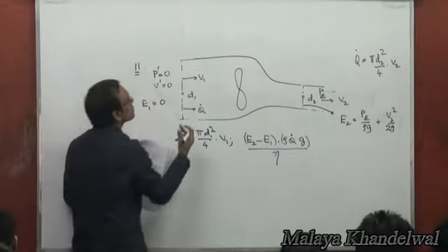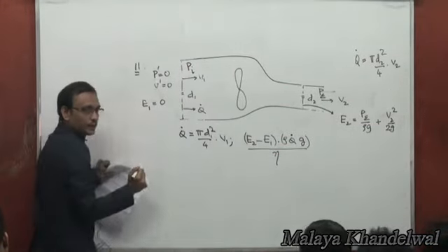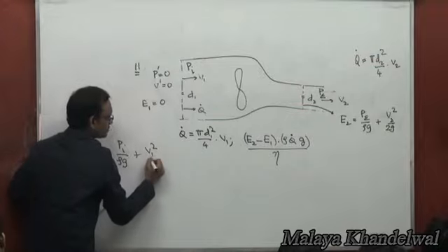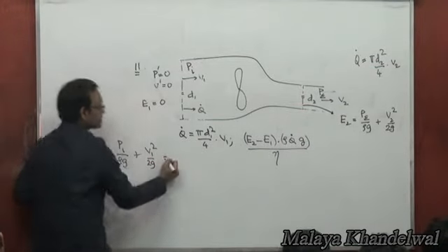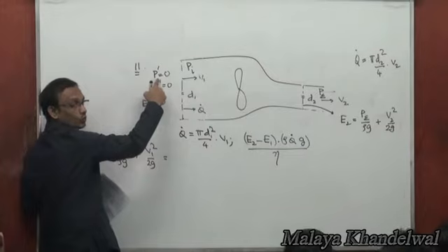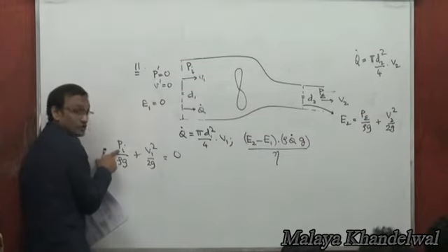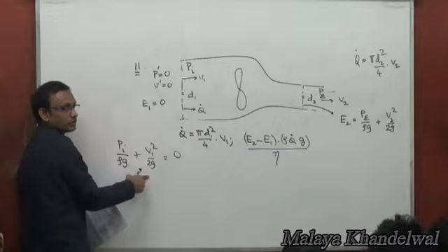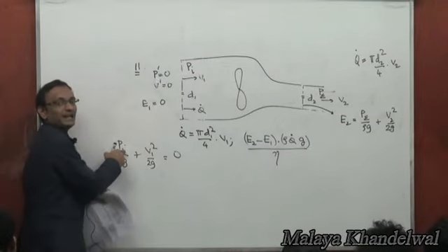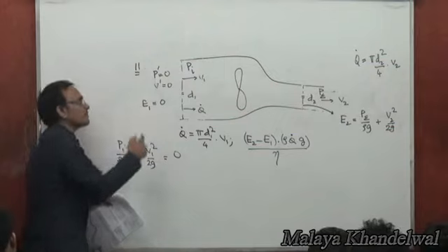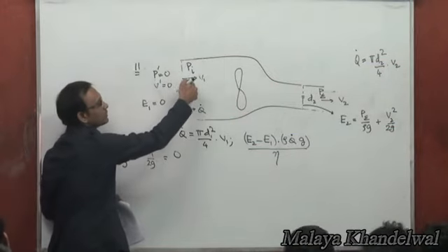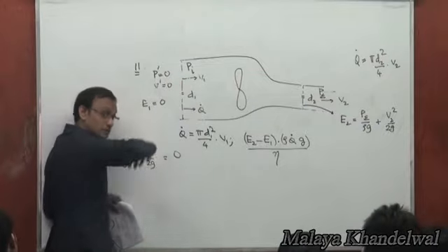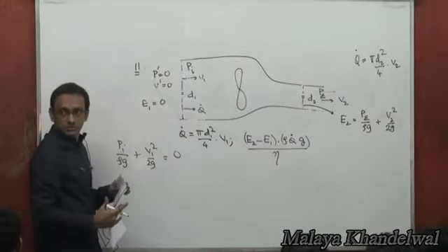That's what happens. So if the pressure at the intake is Pi, then Pi by rho g plus V1 squared by 2g must be equal to the total meters here, which is 0 in gauge pressure. So the gauge pressure here, which obviously turns out to be negative, is minus V1 squared into rho by 2. So you can find the inlet pressure just after entering. Just before entering, it's atmosphere, and it's a suction region of low pressure, lower than atmospheric, so that it could actually induct air in, right? That's what happens.